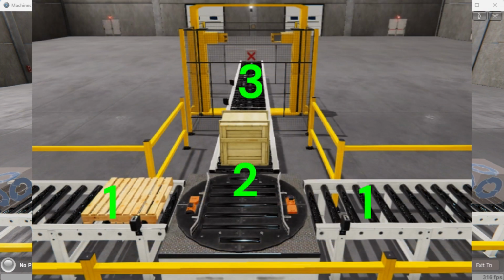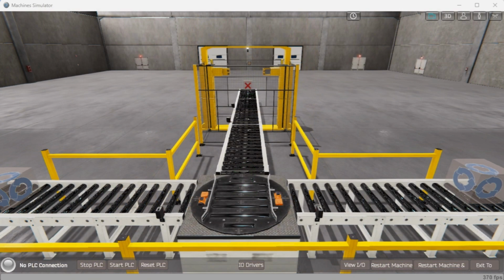Our Click PLC Palletizing Conveyor example will break down into 3 parts: the conveyors controlling the box and skid, the turntable, and the elevator. The box and skid creation will happen if the end sensor does not see the item. This will ensure that a box and skid are always at the end of the conveyor, ready for the turntable.